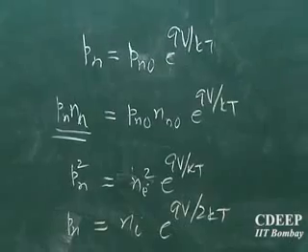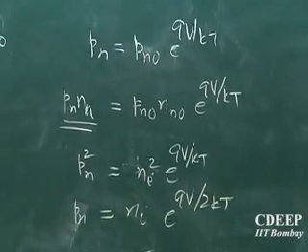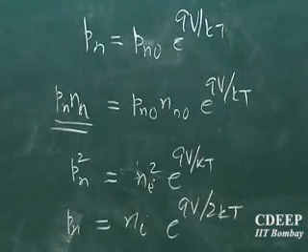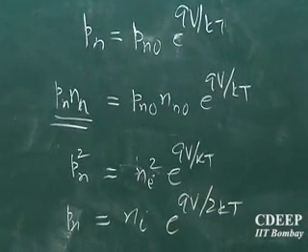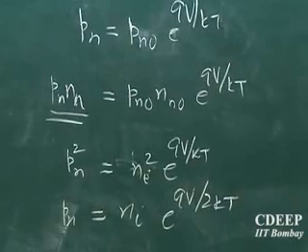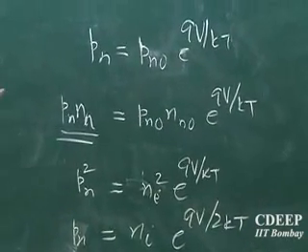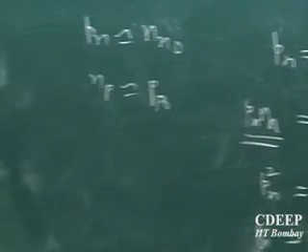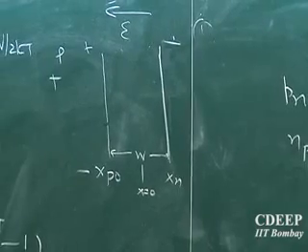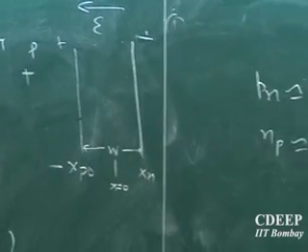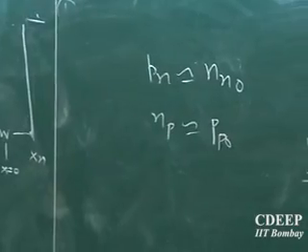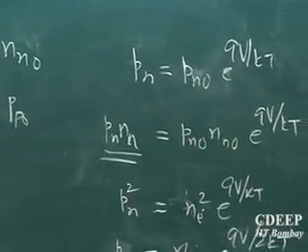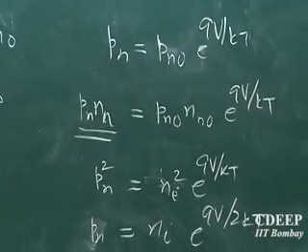So at larger currents, the carrier concentration is now e to the power, what was the boundary condition I applied? It is Pn0 e to the power qV by kT at this point, this is the concentration. But now, this concentration is e to the power qV by 2kT, and if you substitute that in this, your final expression for current will also show an e to the power qV by 2kT term instead of qV by kT.